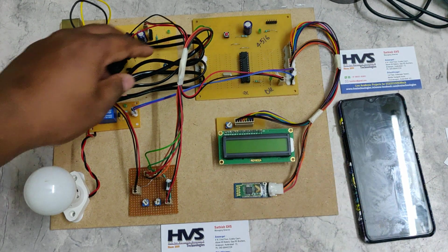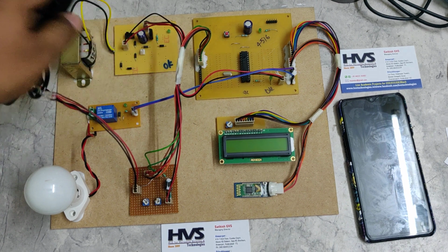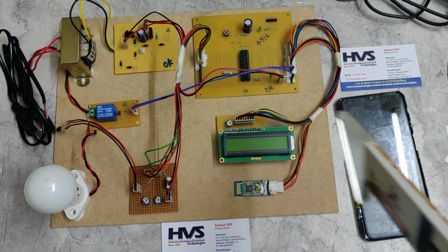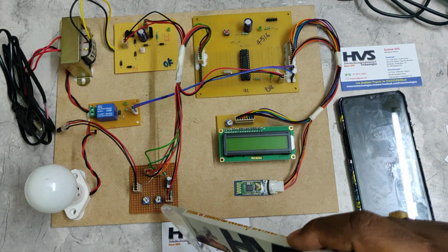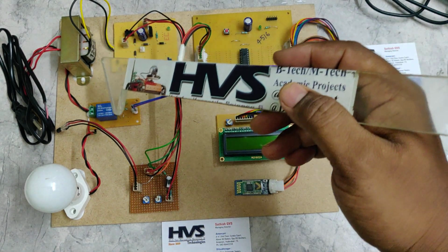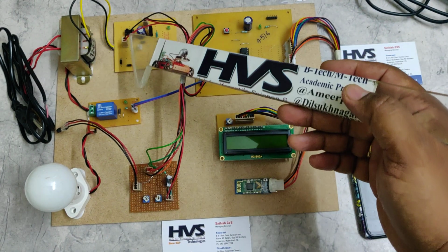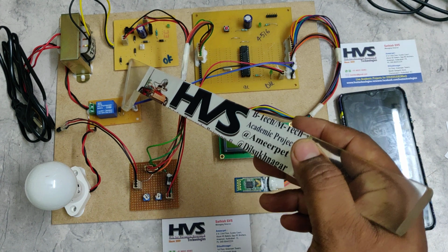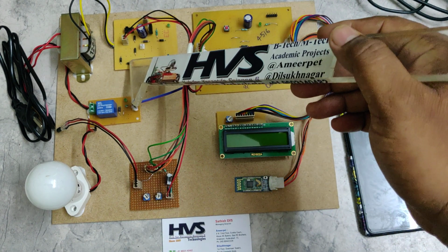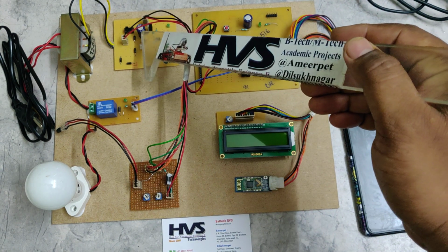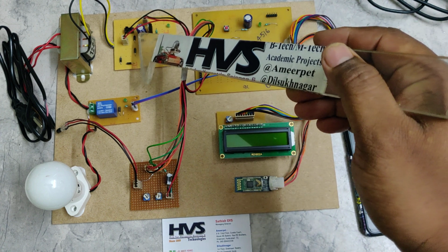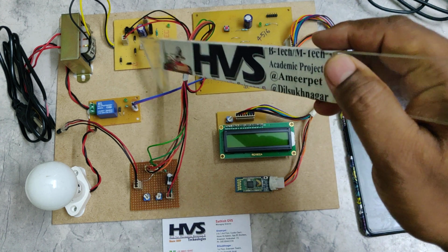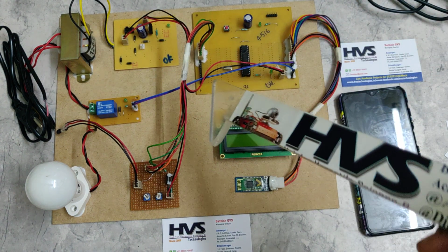And coming to this flow, we are going to provide 230 volts. Generally the microcontroller can't measure 230 volts directly, so we step down the 230 volts to 12 volts AC, and using these 4 diodes connected in the bridge rectifier manner, I will get the pulsating DC. After that, using the filter, we will get pure DC of 12 volts, and with the 7805 regulator we will get the constant 5 volts regulated power supply.